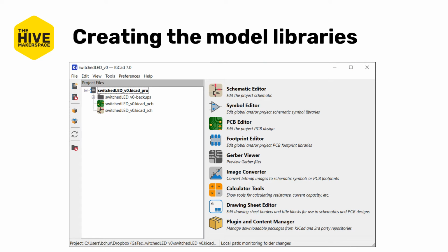So after creating the project, typically the first thing you would want to do is create that single library where all of your components will live. You'd have one for symbols and one for footprints. This would be a living library, as in the components added to this library throughout the design iterations would change and adjust, but try not to remove any components, as you never know exactly what you're going to need again.